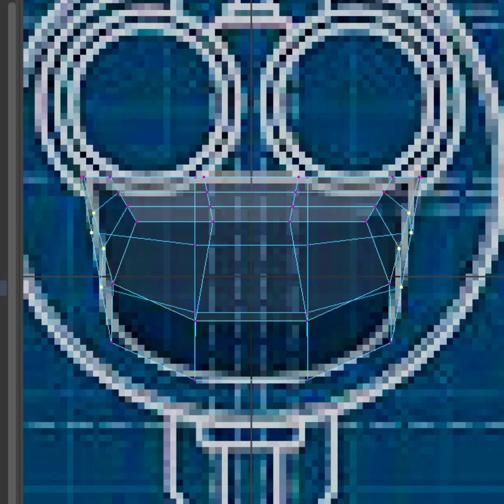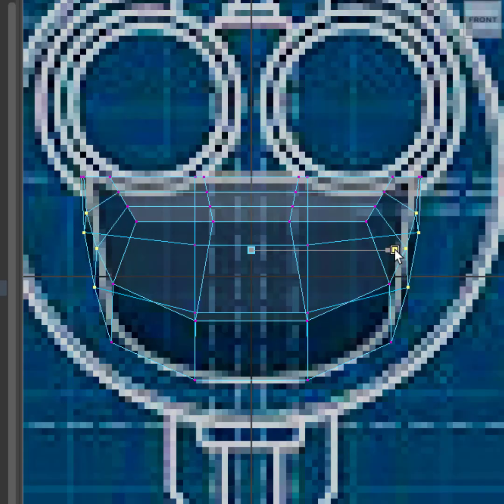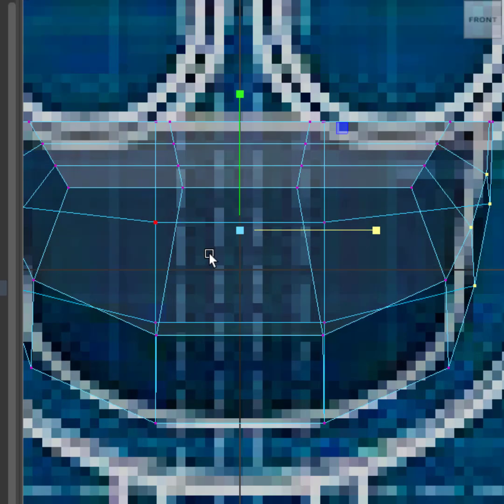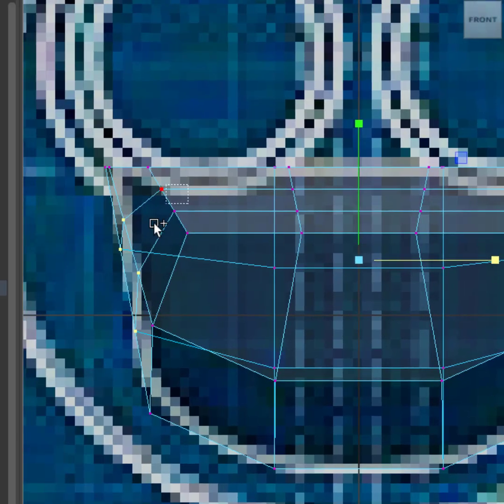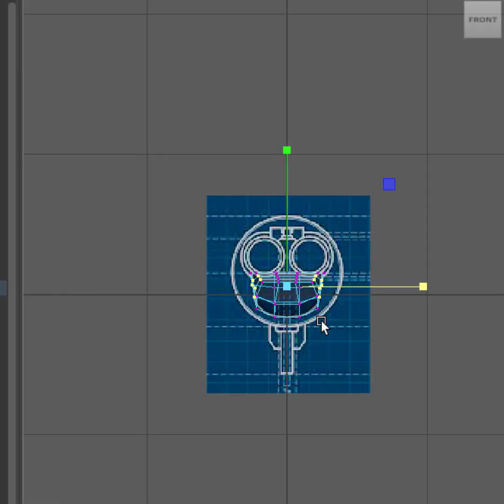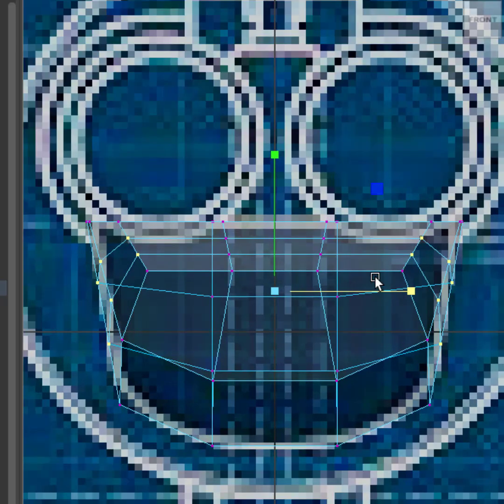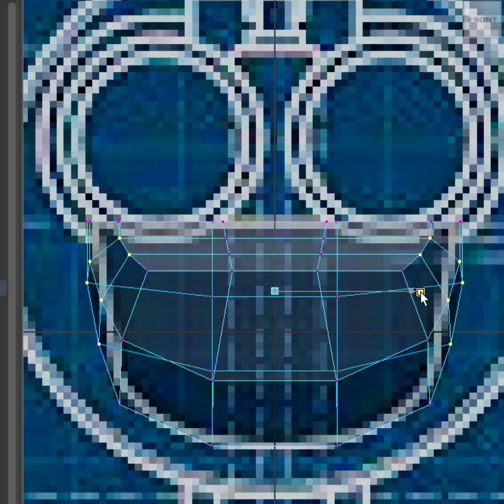And then I will just press R and then rescale there to make it a bit round. I'll get these two also, hold control, hold control this one, the corners only, press F to focus on selected, and then drag. There it is, the roundness for that is achieved.